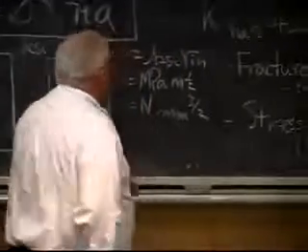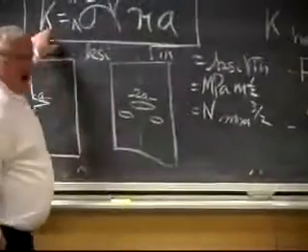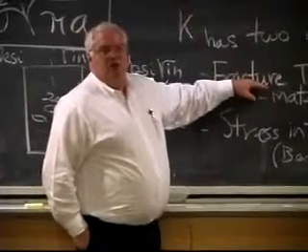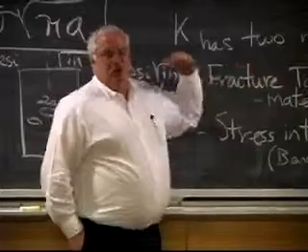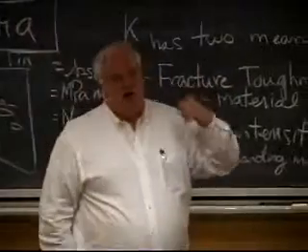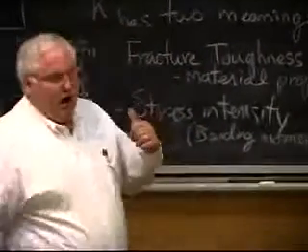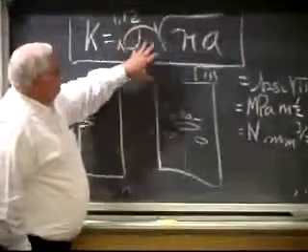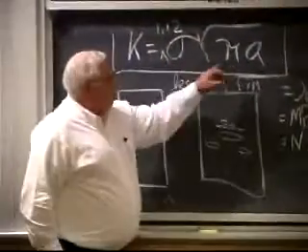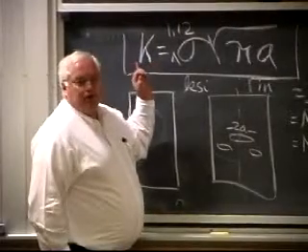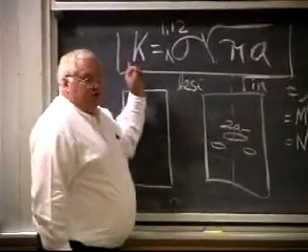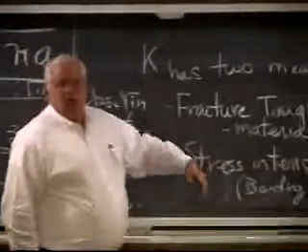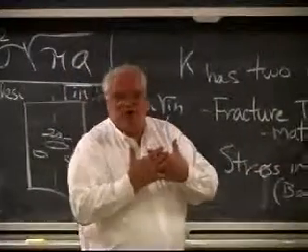Well, regarding the brittleness of the material, K is actually not just a stress intensity, that's the other meaning. K can also be a material property. So this equation is used in two completely different forms. If I want to know whether a structure will fail, I need to know 2 of these 3 parameters: the stress, the flaw size, and the fracture toughness. And if the fracture toughness of the material is less than the stress intensity, then I get a catastrophic failure, which is answering Chris's question.